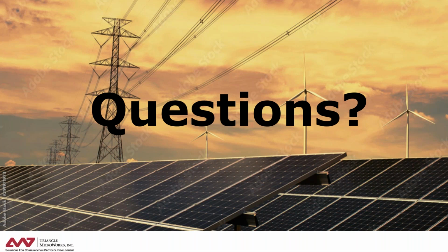I think we're talking about sending analog values from 61850 servers to essentially the HMI and control center. If I understand the question, then absolutely, that's a normal feature of the protocol.